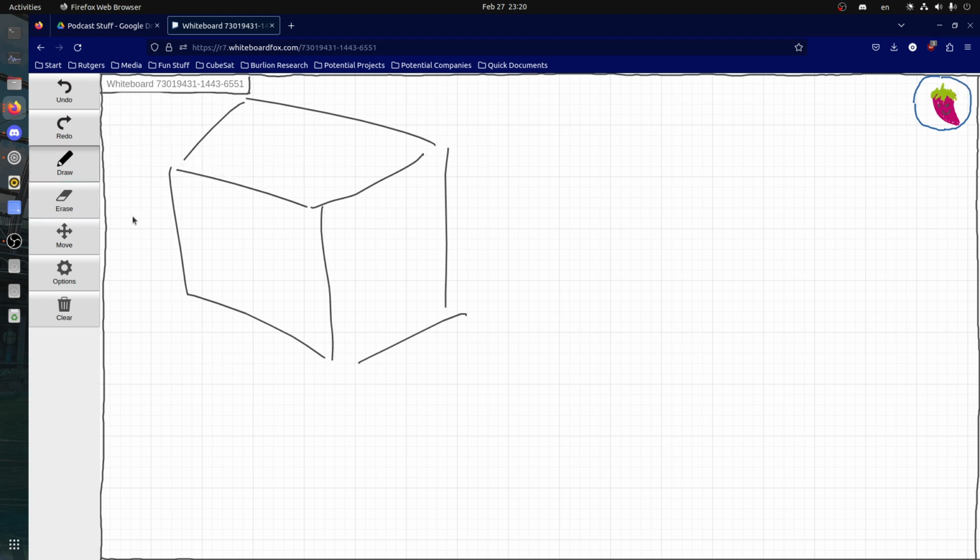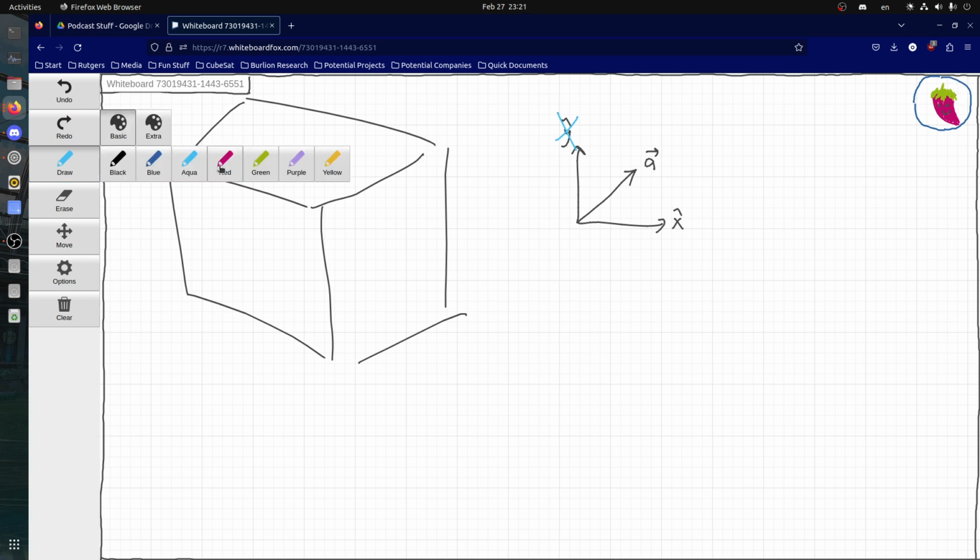We would want four reaction wheels because, in case one fails, it's nice to have redundancy, right? If you have four wheels and one fails, you still have all three axes within reach. Okay. Yeah. I guess if you want to frame this as a linear algebra problem, in 2 dimensions, it's pretty easy. If these three vectors are your basis vectors, and then this is like some other vector A, even if x or y is gone, you can still map out any other vector using a linear combination of these two.